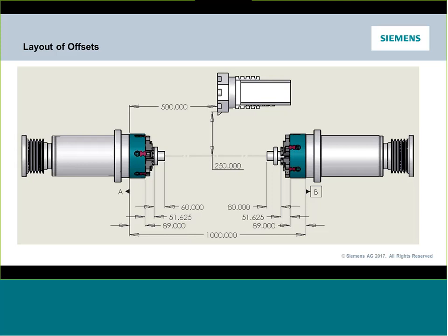Additionally, we dimension the turret coming off of that spindle face at 500 millimeters in Z and then 250 millimeters linearly in X. So this I'm going to use as a safety retract location. You want to make sure you pick a safety retract location that's going to be completely clear of that Z2, that sub spindle sliding back and forth.